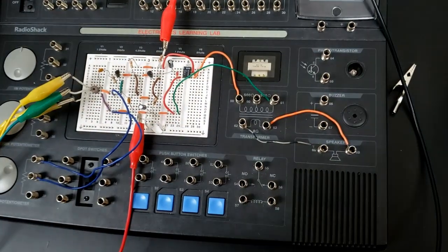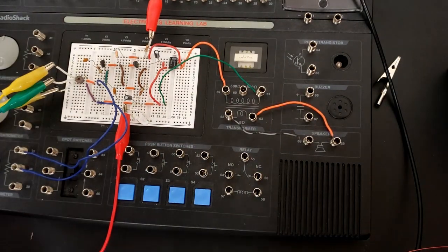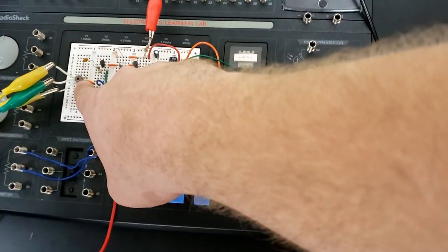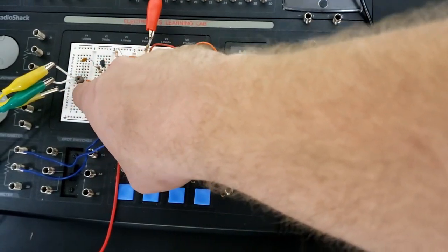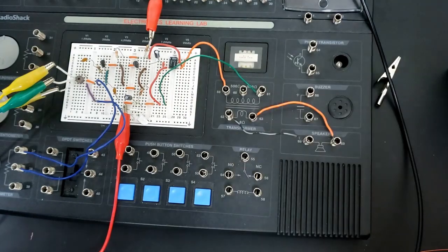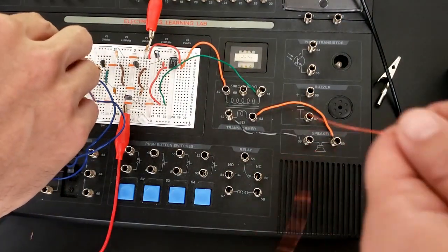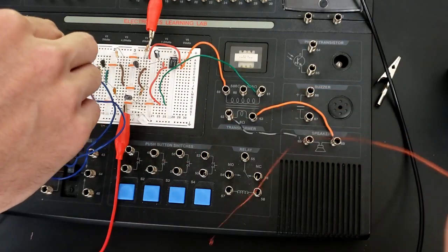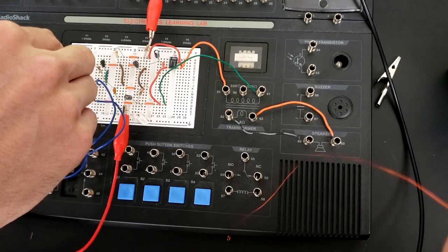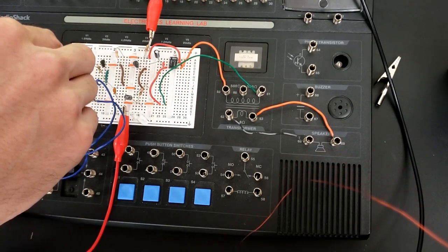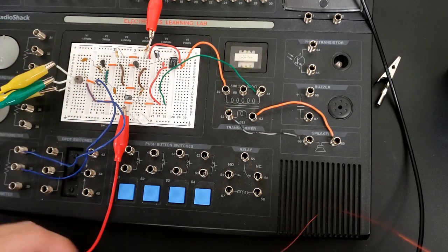All right, so we hear a lot of noise, right, because it's not yet tuned. So what we need to do is start to tune the circuit. So, yeah, here's our variable capacitor. You can change the capacitance of this value just by putting in a screwdriver and turning it. So that's what we're going to do now. So you'll see him turning that screwdriver. And eventually, we should be able to hear our song. All right, there we go.